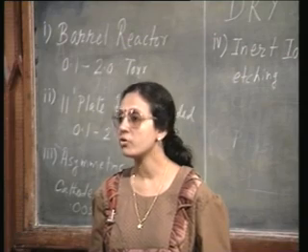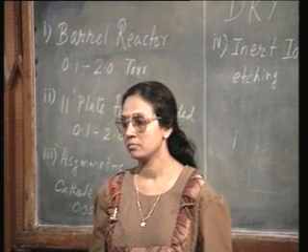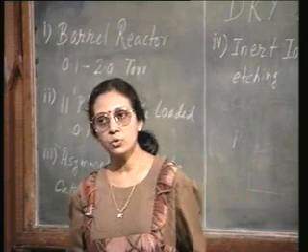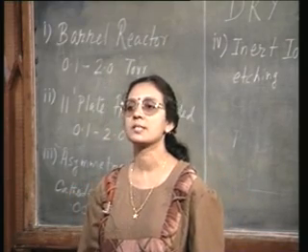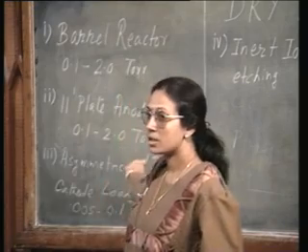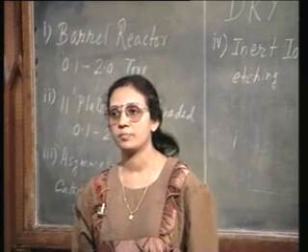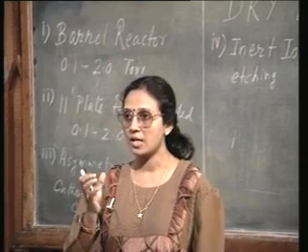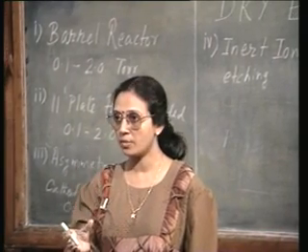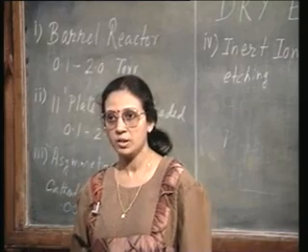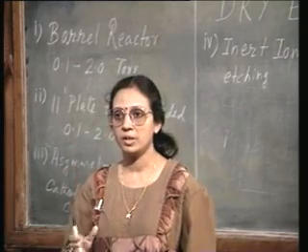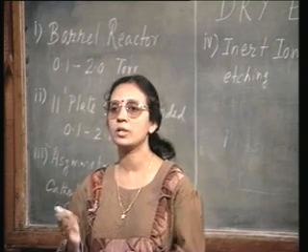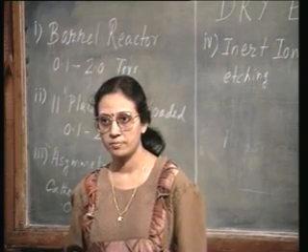So, what we have? We have an inert gas like argon or neon, something like that, and usually these are 2 zone systems. In contrast, all these are single zone systems. The first 3 cases, all these are single zone systems, that is plasma is created in the same place where the wafer is kept. They are all in the same zone. In between the 2 electrodes, plasma is created, and on one of the electrodes the wafer is loaded, right.